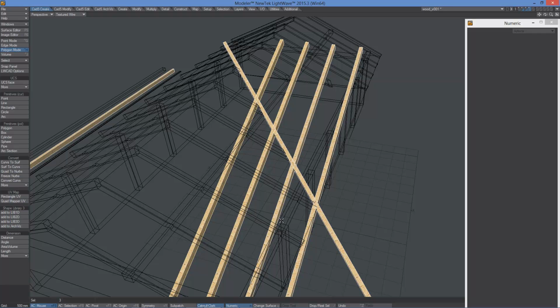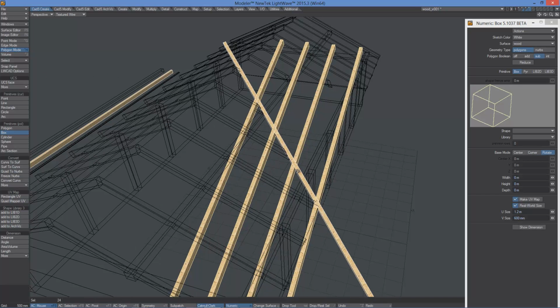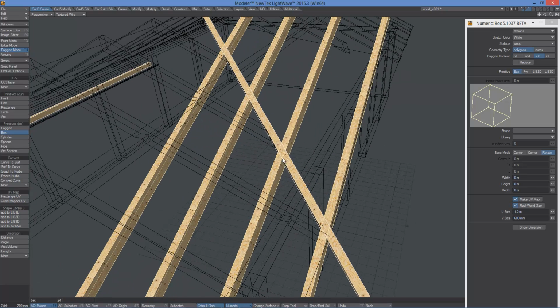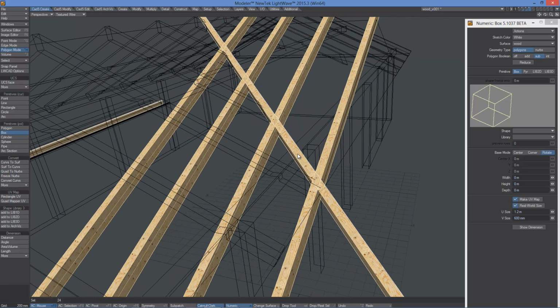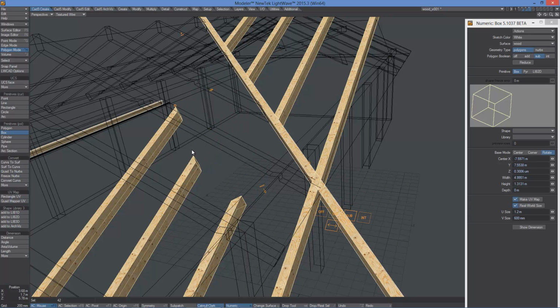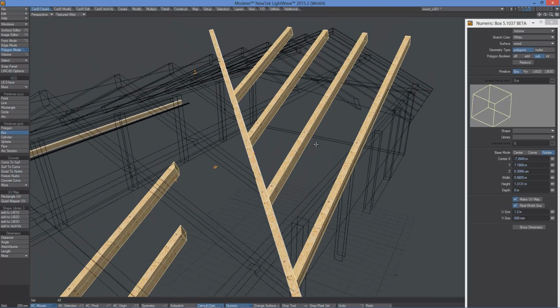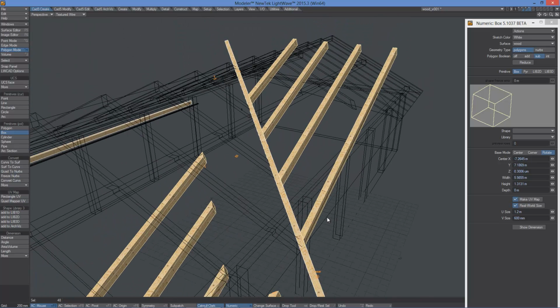Select these 4 beams, and with the box tool in rotate mode we need to cut these 4 beams with the rotated beam, or down from the rotated beam. So with clicking on the top polygon of the rotated beam, we create a UCS plane which is lying on the top of the beam, and we can make a very clean cut which is along this beam precisely.